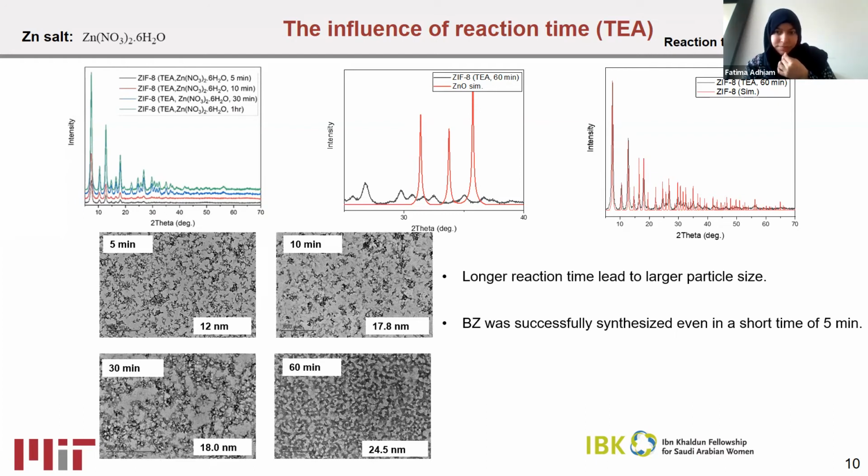of these curves. One thing you mentioned in your presentation was about the purity of the material in these graphs, and if you can just elaborate a little bit on that, that I missed. So usually from X-ray diffraction, if you have a nanoparticle or small particle, we usually have broadening in the peak itself. The broadening of the peak would indicate the presence of two things, either amorphous material or nanoparticle size of the material.